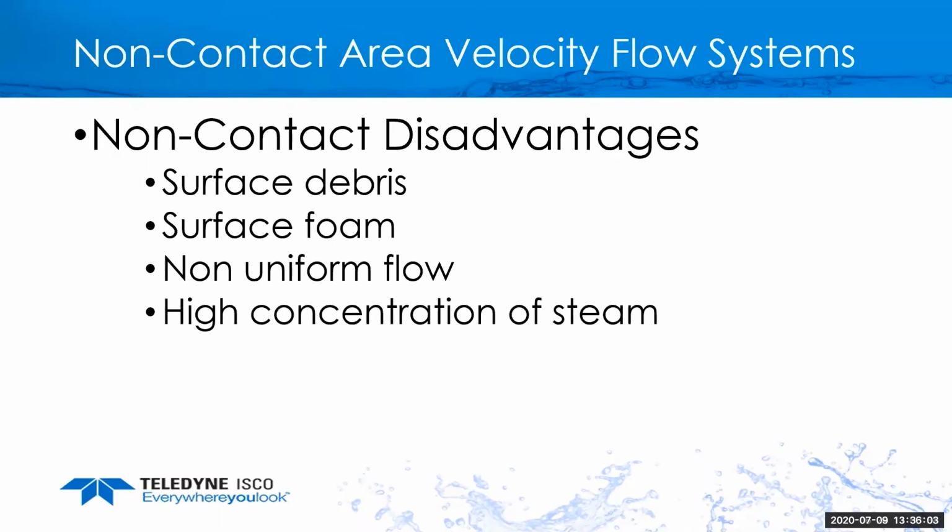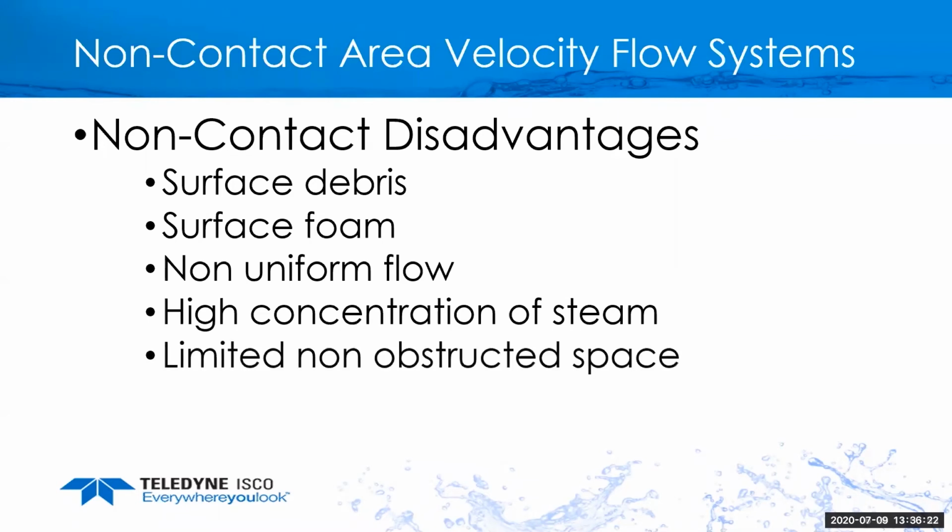High concentrations of steam. This kind of goes hand in hand with foam. We don't want a lot of steam, typically on any device. Radar may work a little better with steam than maybe the laser, because I don't think it's affected by steam quite as much. But again, in general, you want to keep away from that if you can.